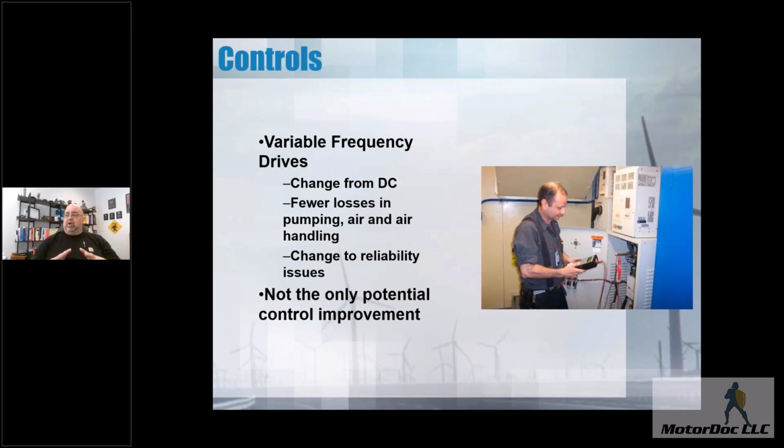The challenge we run into with variable frequency drives is the introduction of harmonics, because the majority of people purchase these things and put them in place. They've either been sold on the fact that it's a clean drive, or they've been sold on the fact that you don't need to put in filters, et cetera. Plus, the grounding on these systems will often put a noise into the ground.